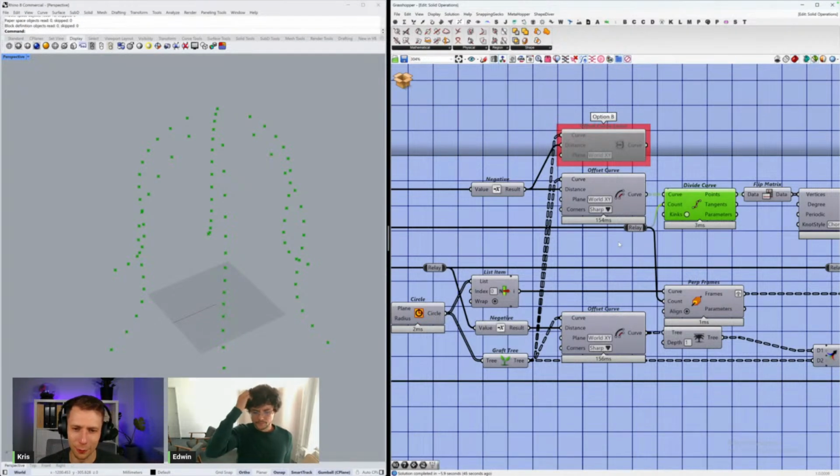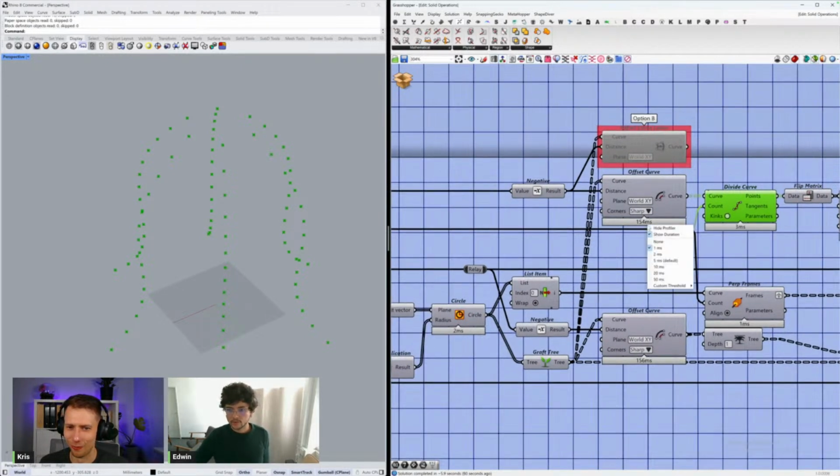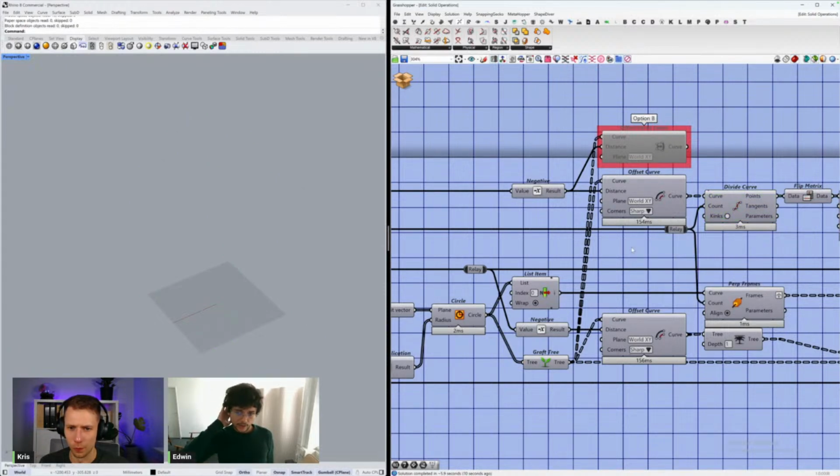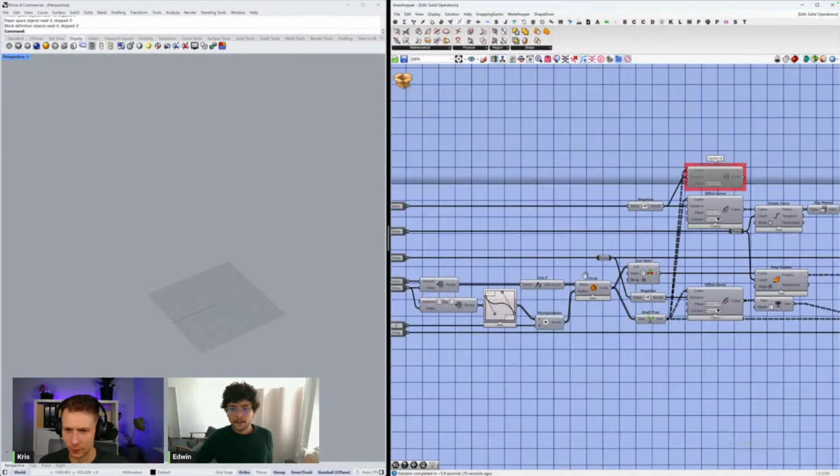For sure, this will also slow down your script if every component has this small widget. If you think about having 1,000 components in your Grasshopper, this will also slow down your work. So here I'm showing it for this amount, but it's just because we are focusing on that. Here you can also decide when to show it and when not. There is even a custom threshold. And that way we can easily start to see which components are taking the most in this one.